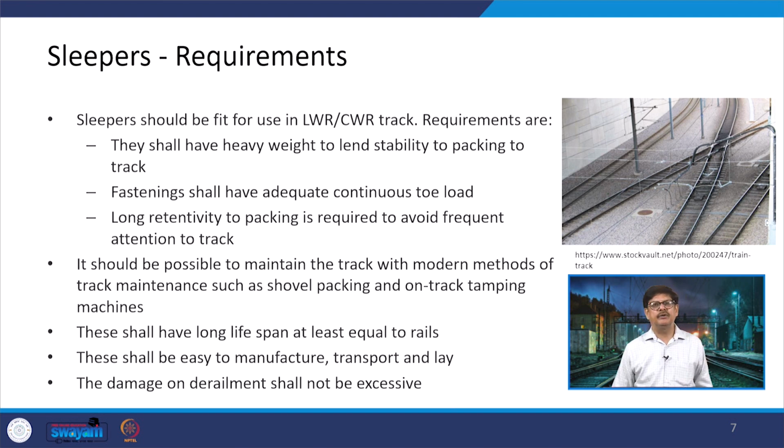In that particular direction, the requirements are that they shall have heavy weight to lend stability to packing of the track. The fastening shall have adequate continuous toe load, and there shall be long retentivity to packing so as to avoid frequent attention to the track.